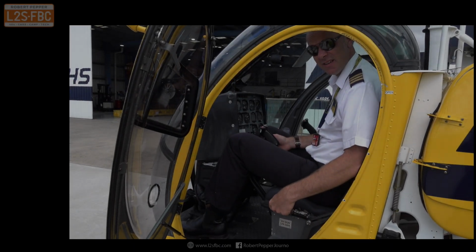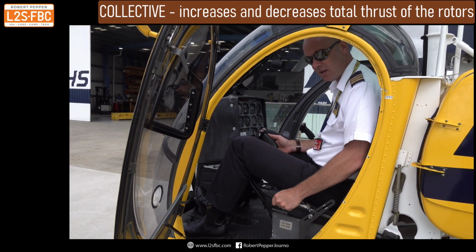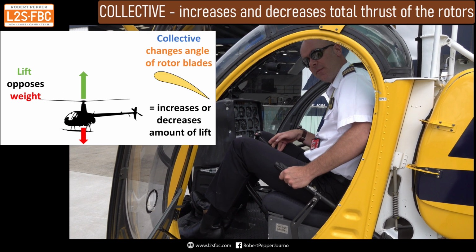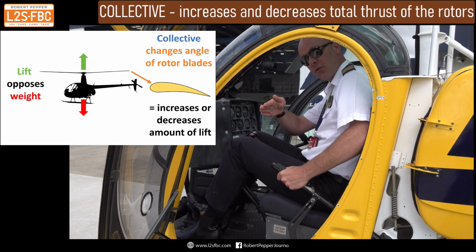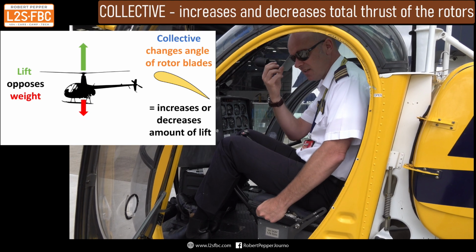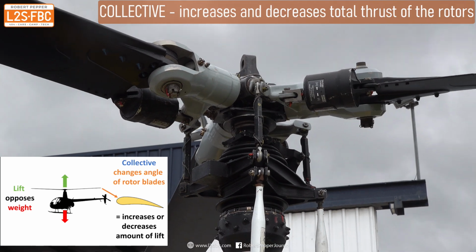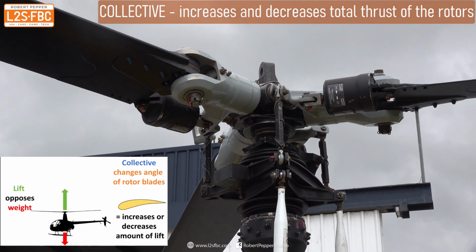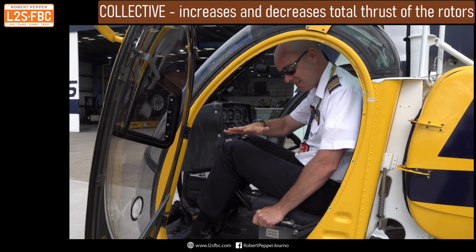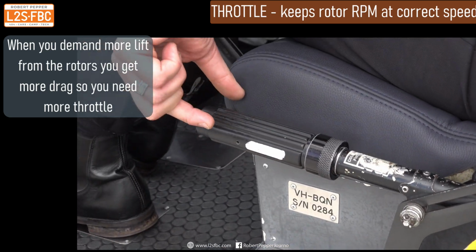Starting off with the collective, guys, as the name says, collective, it actually changes. As I raise the collective, it changes the pitch of all the blades collectively. Same amount, same time, increasing the lift of each blade, and as such increasing the rotor thrust, and as a result the helicopter will start to climb. The opposite effect as well: you lower the collective, you decrease the pitch collectively on all the blades together, and the helicopter will descend.